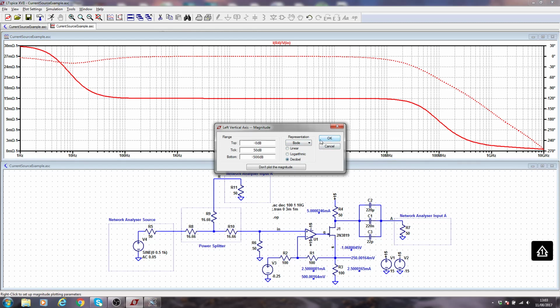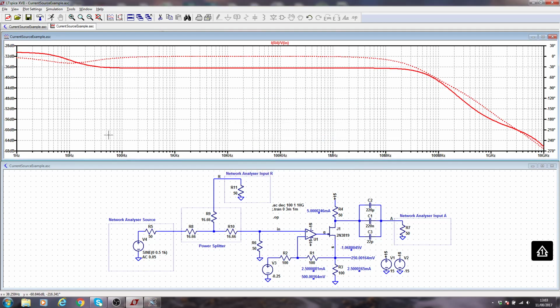Decibels, there we go. Wow, that's a low number. So I'm interested, I've got pole 0 here. So for those of you in 225, yay, pole 0 is great. Then we have a mid-band, which is the region of flat frequency and minimum phase shift. And then at some higher frequency we have a 3 dB point where we've got to roll off, and it looks like we've got, don't know how many dB per decade that is. This is not going to quite get to a decade, but if it did, it would be there-ish.